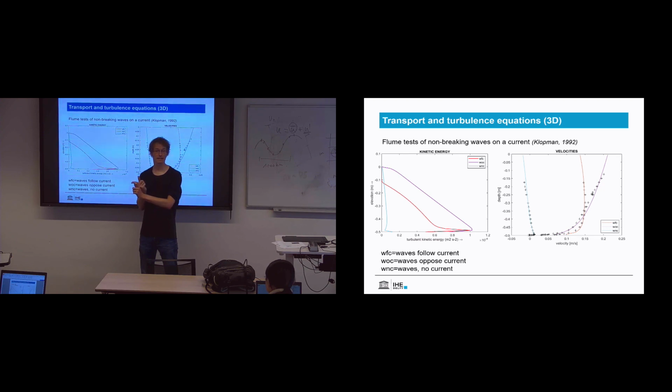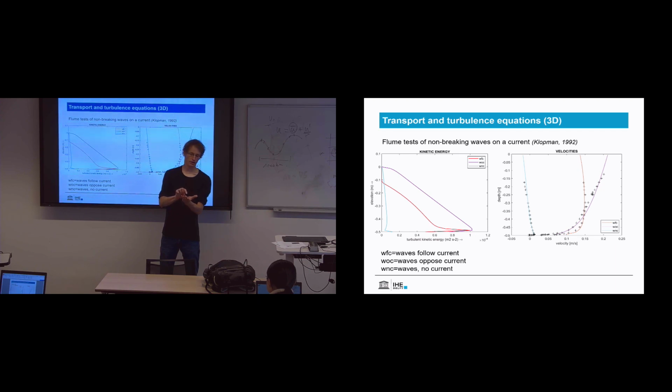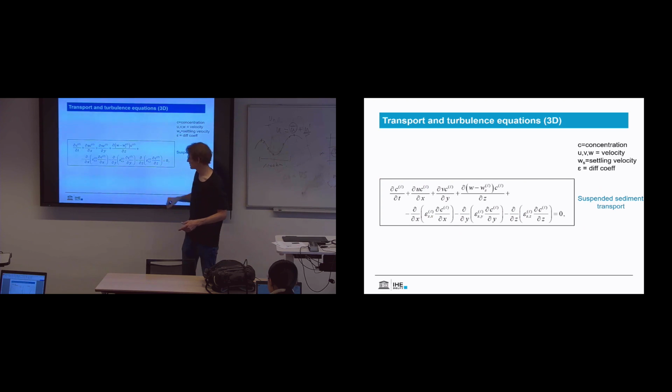If you have a wave traveling over a bottom, you have orbital velocities, right? But if you're near the bottom, in the bottom boundary layer, then this orbital velocity is a little bit faster at the top than at the bottom. That means that you don't have a zero component of the vertical velocity at the moment that you have your maximum horizontal velocity. The effect of that is a little net force in the direction of the wave propagation, so that drives a little velocity. That plays a role here, because that's this little dink that you see here.